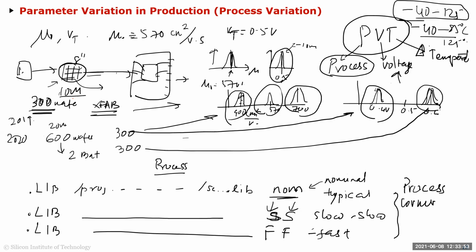Okay, so when we do the lab, I mean, you've already done the process variation, hopefully. So it's basically batch to batch. Every time they're fabricating in a batch, your parameters, your mobilities and your threshold voltages, they can vary. But they'll give you bounds. It's not like they can vary all over the place, because then it's unpredictable. They'll give you predictable bounds. And these bounds are the corners, basically.